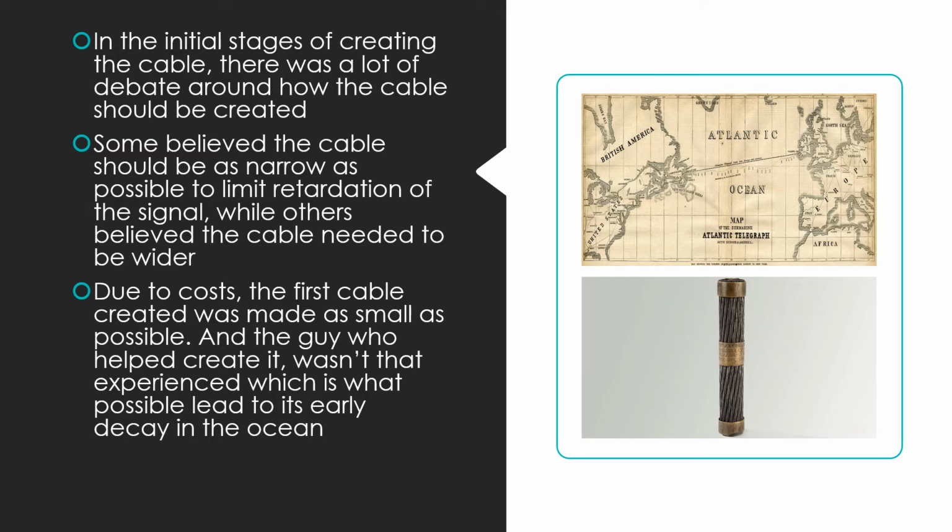Over the ensuing years since the first transmission, techniques improved with the addition of inline amplifiers, or repeaters, to allow the signal to be propagated across longer distances, and progressive improvements in signal processing improved the capacity of these systems. Eventually, telegraph turned to telephony, valves turned into transmitters, and polymers replaced rubber, but the basic design remained the same: a copper conductor sheathed in a watertight insulating cover, with steel jacketing to protect the cable in the shallower landing segments. The cables that are in the ocean today are about the size of a garden hose and can last up to 25 years, if not longer.